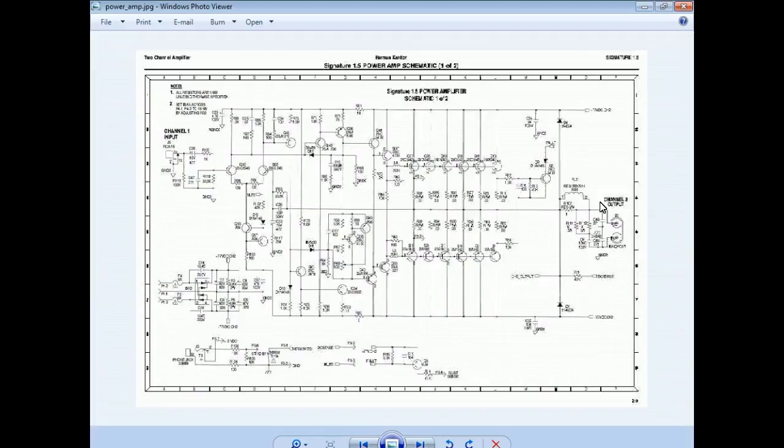It's the battery, because the battery not only has to deliver the power for the speakers, it's also got to power the amplifier, right? You understand? If we got any Class A's in there, we're going to have to buy those things off. These are mostly Class B's, but these guys are still a maximum of 75% efficient. Right? You understand? So that means if I get 75 watts out, I have to put 100 watts in. Right? So your battery's got to not only power the speakers, it's got to also power the what? The amplifier. Right? You understand that? Which is pretty interesting. I'll try to find that thing and look for it.